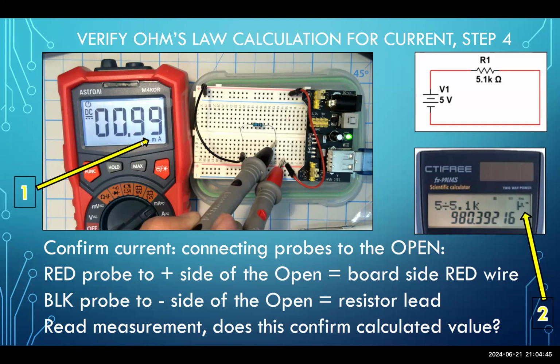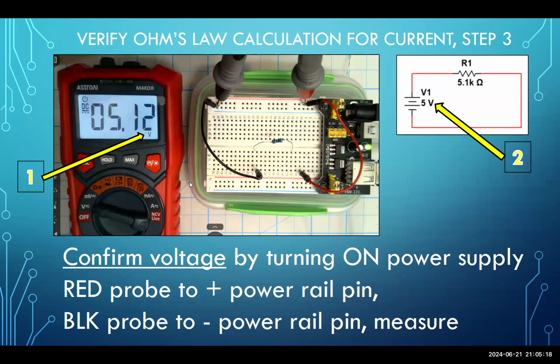It might, for whatever reason, show this as 1.00 milli, a whole milliamp. And a whole milliamp is 1,000 microamps. And again, given the tolerances or margin of error, it's not a whole lot far away from 980 micro. So don't fret if your digital multimeter shows you 1.0 milliamps, but hopefully it shows you something that is a decimal 0.99 or 0.998 milliamps, and the decimal milliamps does work out to be microamps in the conversion process that I showed you. Okay, we're done with this.